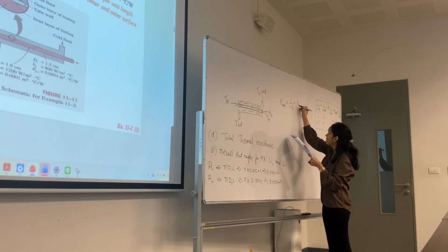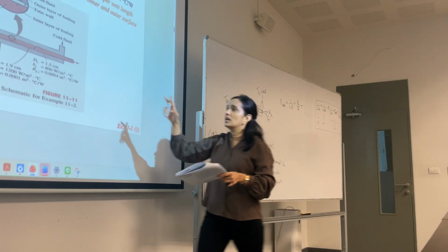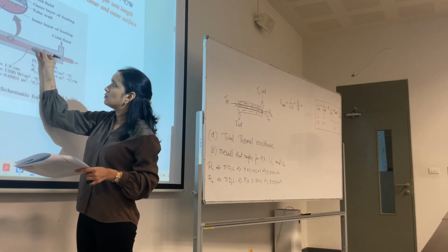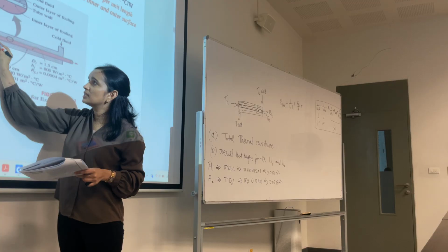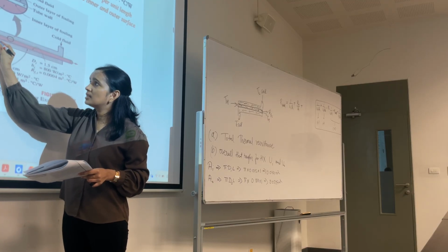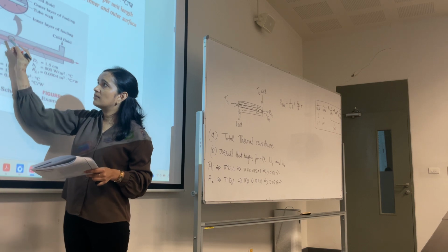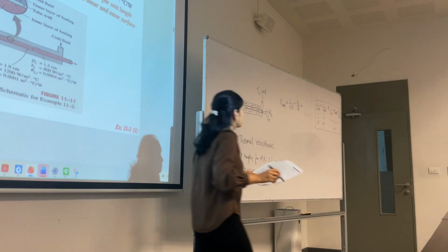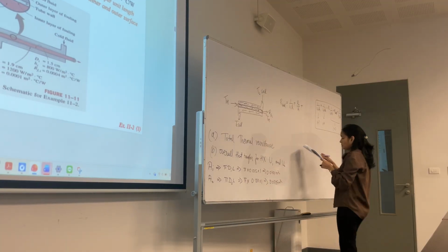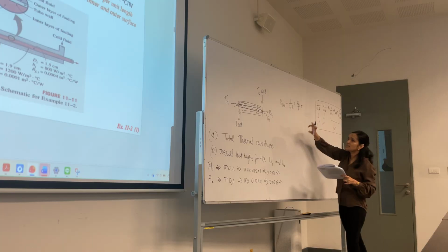Fouling factor is given inside as well as outside. So this is inside. The heat transfer inside, from the water, is by convection. Then this is a wall, a very thin wall, by conduction. And then there is also a fouling factor, a resistance, so we add that. Then we come outside, and this is also again convection. So this is our wall. Our wall in this case is a cylinder.